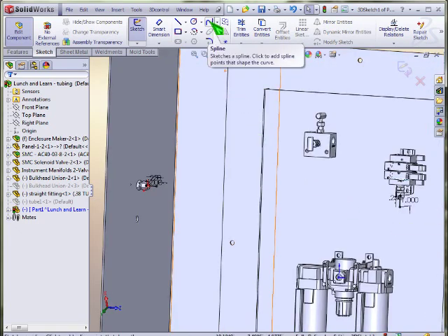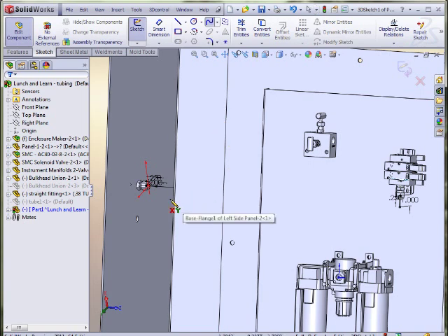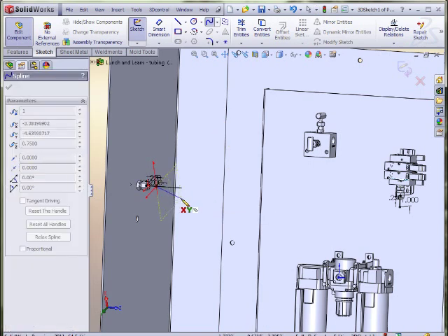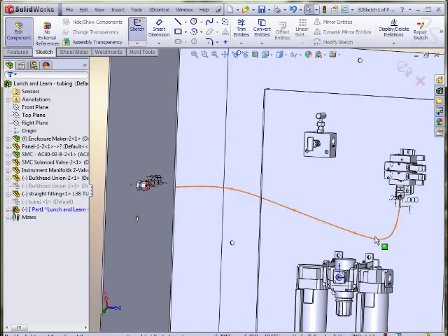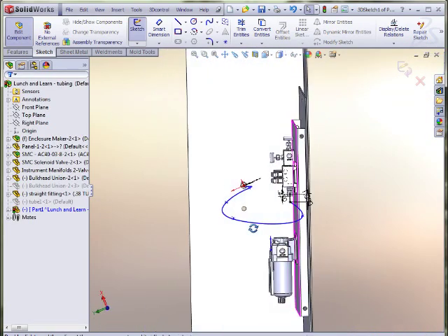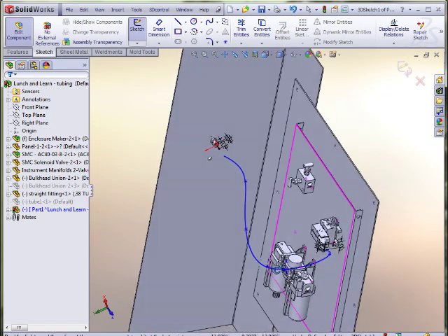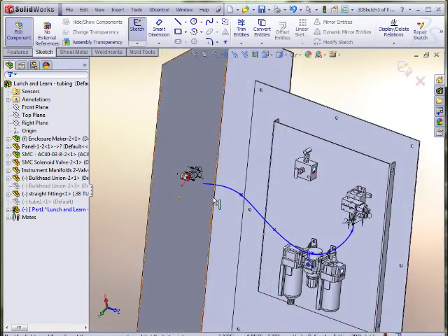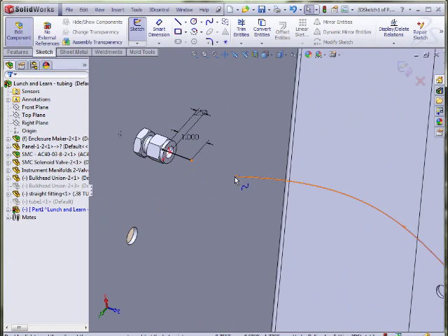Now we'll use the spline command. This would be similar to flexible tubing as opposed to an orthogonally bent tube that we created the first time around. You can use as many spline points as you want to. Here again though, make sure you use that tab key in order to get the wire, or spline, going in the direction that you want. This is going to be a little tricky, but there's plenty of ways that you can make this work.